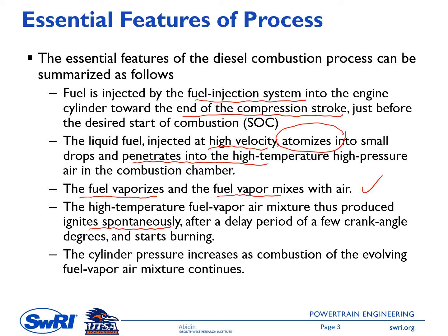So in this step you can see the principal difference between the spark ignition and diesel combustion engines. Because of high pressure and high temperature, the mixture of air and fuel vapor ignites spontaneously, and this spontaneous ignition occurs after a certain delay period.